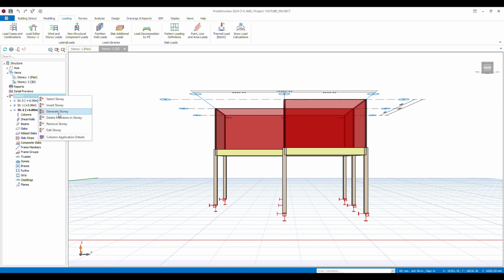So the roof beam is not carrying a slab, except if there's an architectural requirement where a slab supports a tank or so. But in this scenario, I'm assuming that the roof beam is just carrying its self weight, so I'm not loading the roof beam. So the design is based on that condition, but in reality, the roof beam is not just going to carry self weight. It's going to carry the roof and other environmental loads, like snow, depending on your region, and it's going to carry rain.